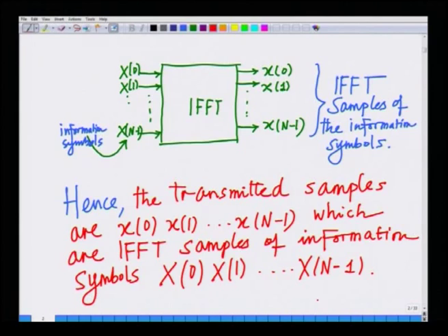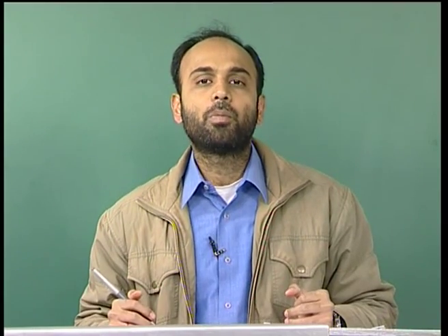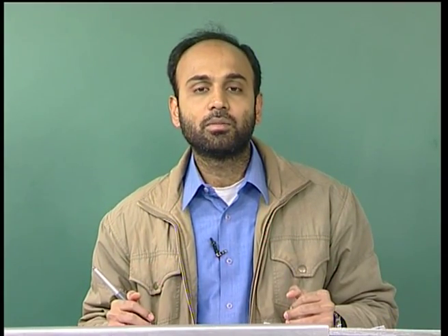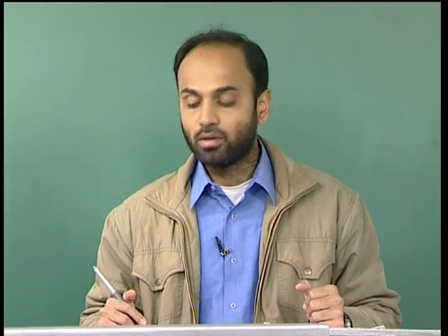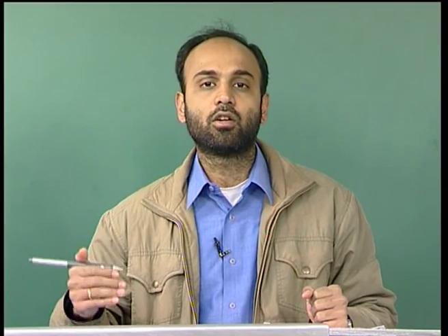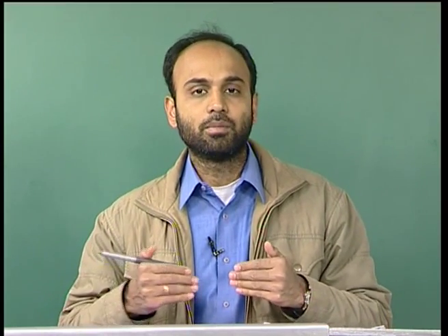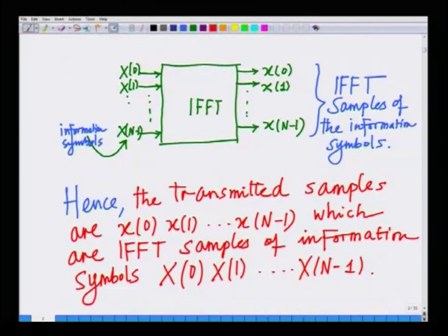So, in OFDM, as we are very well familiar, we are not directly transmitting the information symbols, but before transmitting the information symbols, we are performing an IFFT operation over these information symbols, and we are then transmitting the IFFT samples. Alright. So, this is what we already know about an OFDM system, that we are not transmitting the symbols themselves, but we are taking an IFFT operation before transmitting the symbols.